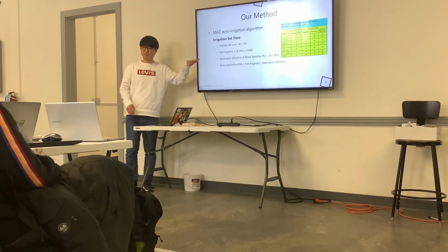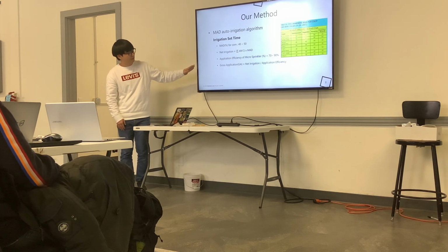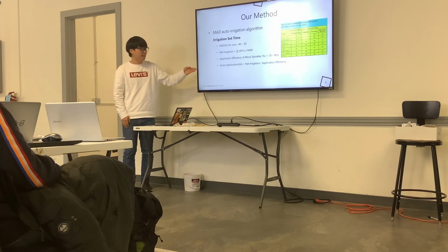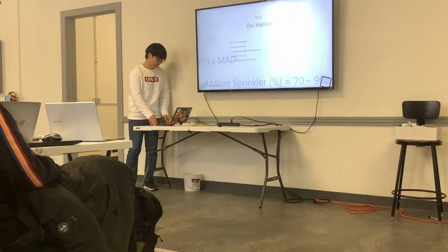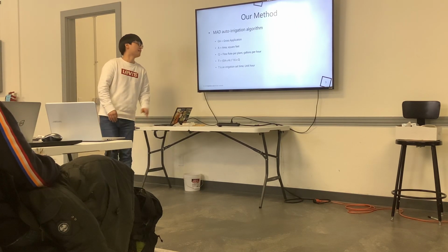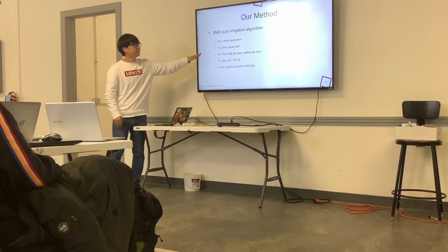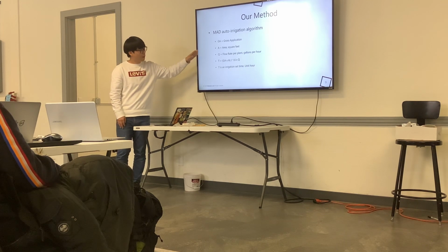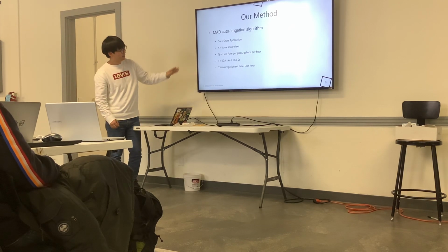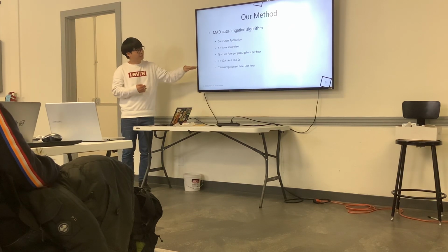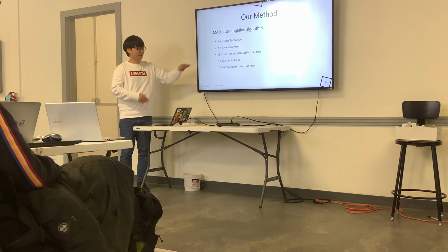And if you have a lower efficiency sprinkler, you should use more water, so gross application will be higher. Then with the GA we have already got, A stands for area in square feet, and Q stands for flow rate per plant in gallons per hour. So using this formula, we can get how much we have to irrigate.